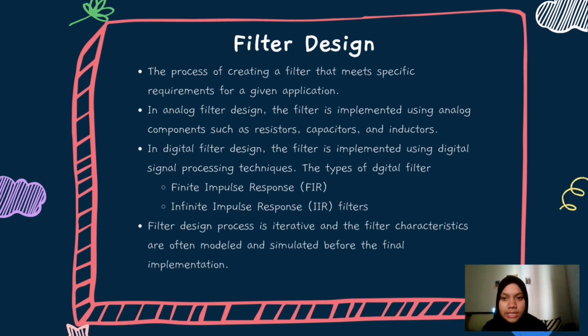In analog filter design, the filter is implemented using analog components such as resistors, capacitors, and inductors. The most common types of analog filter are low pass, high pass, band pass, and band stop filters. The design process typically involves selecting the appropriate filter topology, determining the cut-off frequency, and then calculating the component values using techniques such as Butterworth or Chebyshev filter design methods.